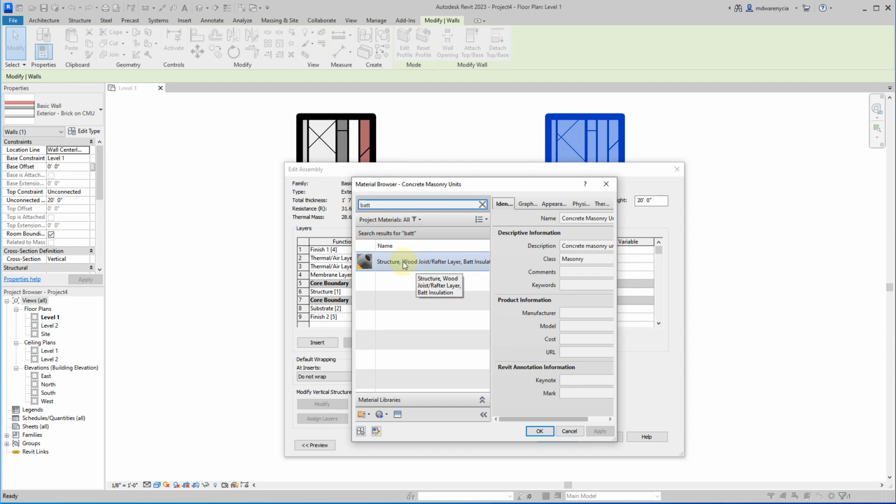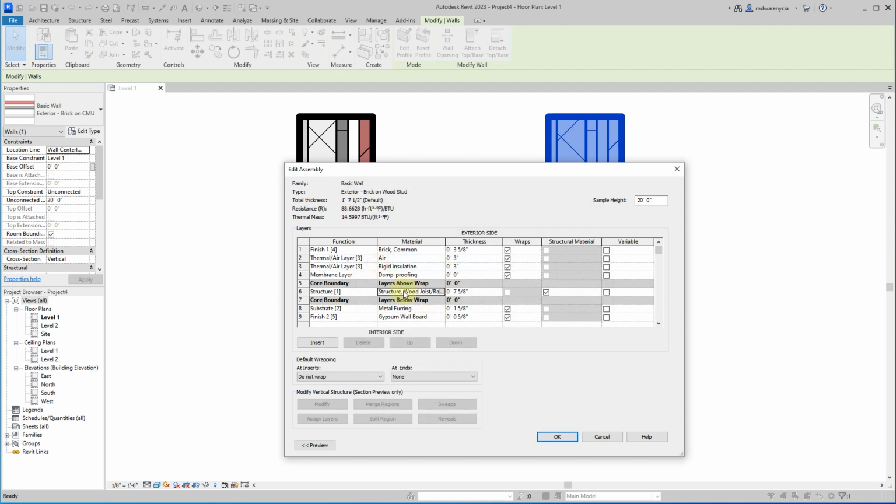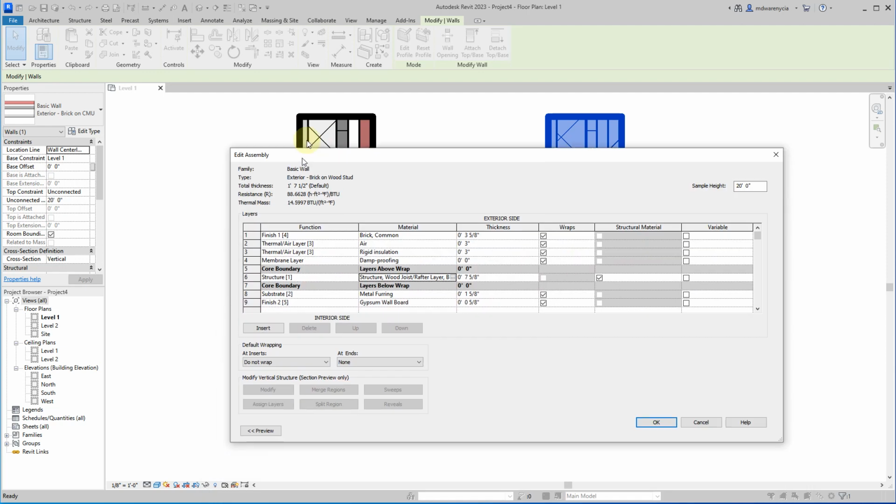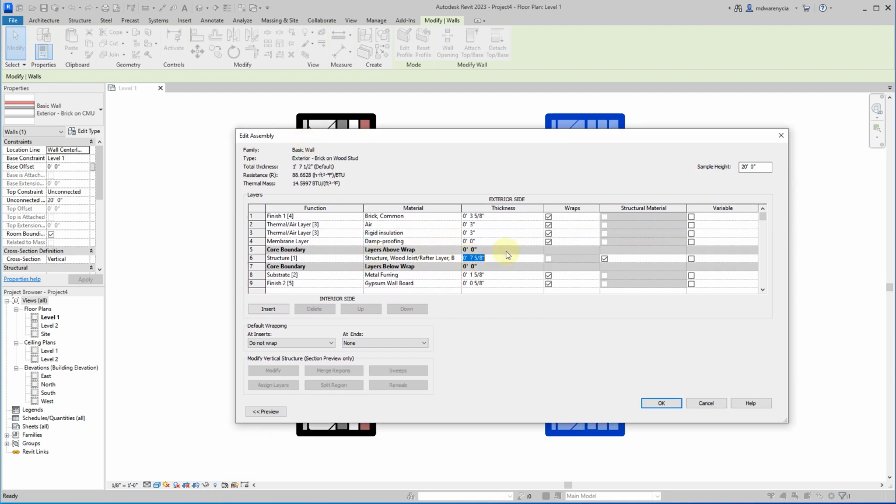And so this is going to be what I would use every time when you're setting up a wall. Just change that material so that it changes your value. Let me drag this out. So it changes the value here for the material. Now, in this case, I want to get something that's very different from this original wall that we're starting with. So I'm actually going to change this to 4-inch. We're going to call this a 4-inch nominal wood stud, which, because it's nominal, is going to be 3.5 inches. And we're going to keep that checked as it is.